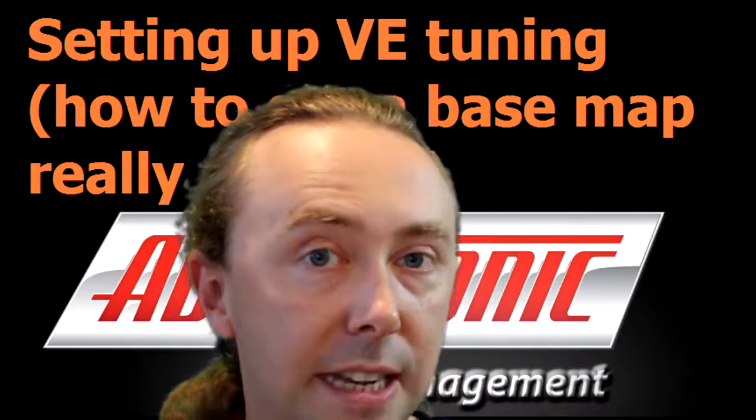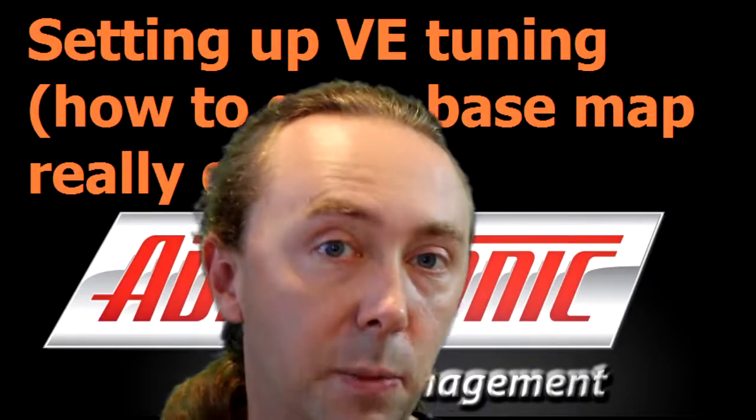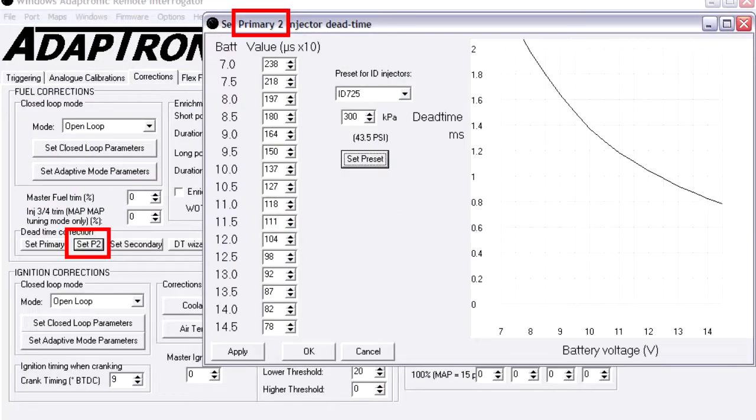If you're using 2 stages of injection, as on an RX-7 or the Series 2 RX-8, then you need to make sure the primary 2 injector size is set to 0. And if you're using 3 stages of injection, as on the Series 1 RX-8, then set the primary 2 injector size to your secondary set of primaries, and also set up the primary 2 injector dead time.